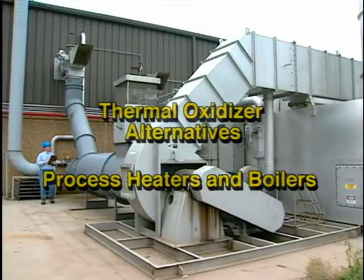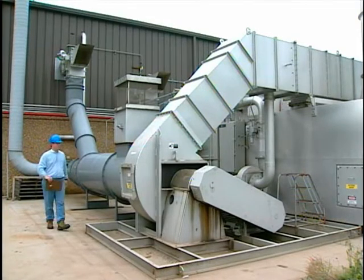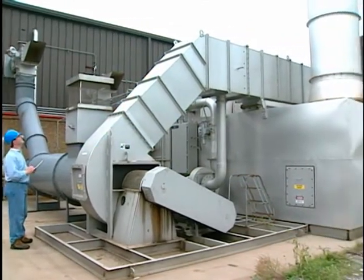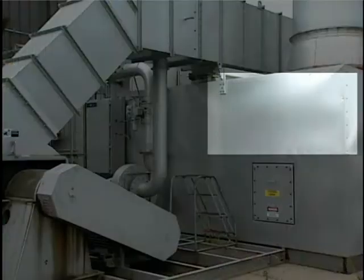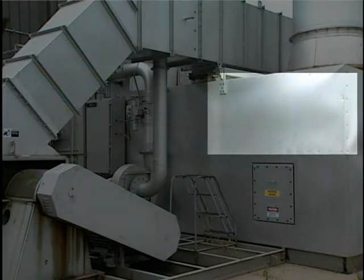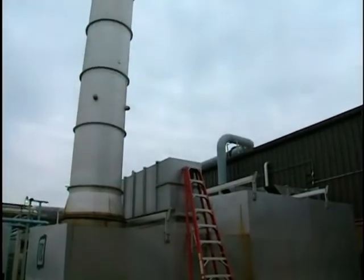An alternative to installing a thermal oxidizer is to incinerate the contaminated gas stream in a process heater or boiler. This avoids the capital cost of new equipment. The contaminated gas stream is typically injected close to the main burners or may be used as part of the combustion air supplied to the burners. Process heaters and boilers are normally designed to operate with combustion chamber temperatures greater than 1,800 degrees Fahrenheit and with flue gas residence times in excess of 1 to 2 seconds.